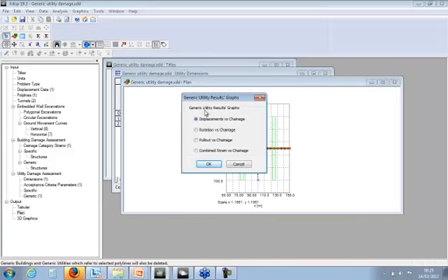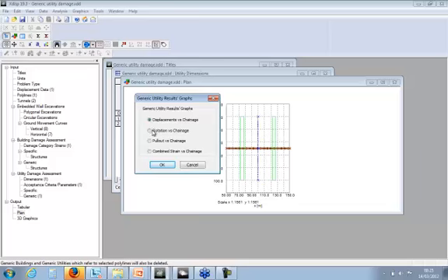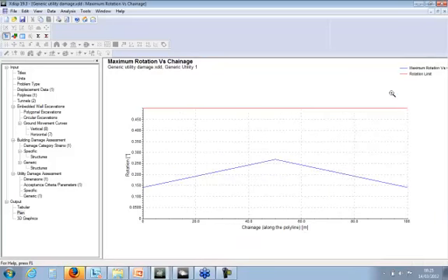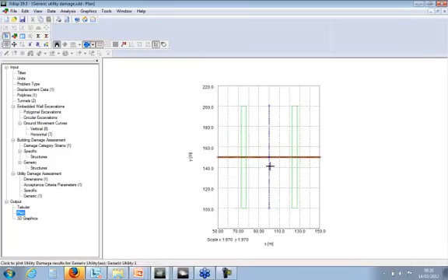So you can choose, for example, displacement versus chainage. Where's the worst case displacement along that polyline? Where's the worst case rotation along that polyline? Pull out or combine strain. So if I look at rotation, you can see the maximum rotation is here and a rotation limit is here. And you could also see that here's the rotation along that polyline. So the worst case rotation for my utility is along the middle area. So that's a change along the polyline, and it's well within the rotation limit. But if I look at the worst case rotation in plan, it's where you would expect it to be. So it's along the center here of the polyline.